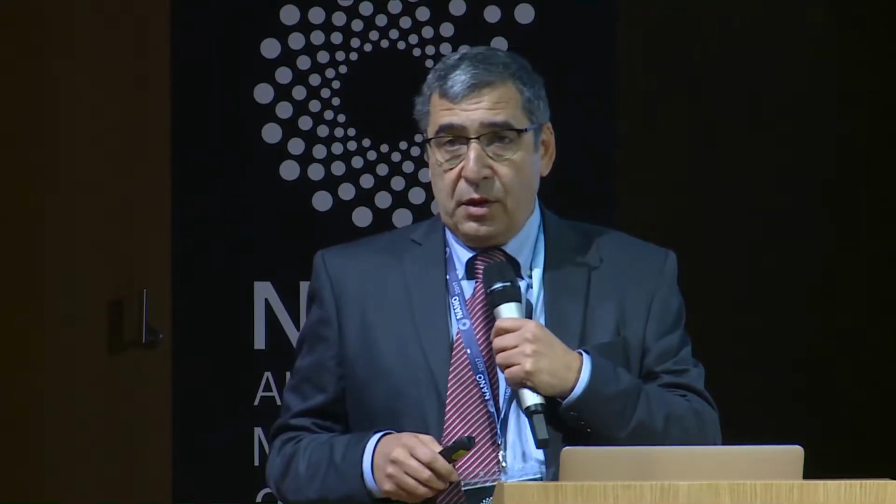The talk that I will give in this 15 minutes is about a program that we are doing together with Coaxial and with some other partners, and it is related to having a transparent cathode on top of OLED. Carbon nanotube is a very good material if you can control the dispersion of the material to put on as a transparent cathode, because you can control the transparency, you can control the conductivity, and above all, you need to control the work function, as we will talk in a minute.